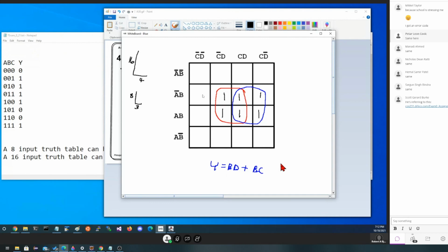We now know we only care about two variables. Well, I could see use of 3 of them here. Oh, yeah, sorry, 3. Okay. So we could say our table has as headings B, C, D, which gives us Y. And now the advantage of this is that we have 8 lines in the table, meaning this is the non-reduced form, and we should be able to get it down to 4 on that side and 2 underneath. So let's see if we can do that.